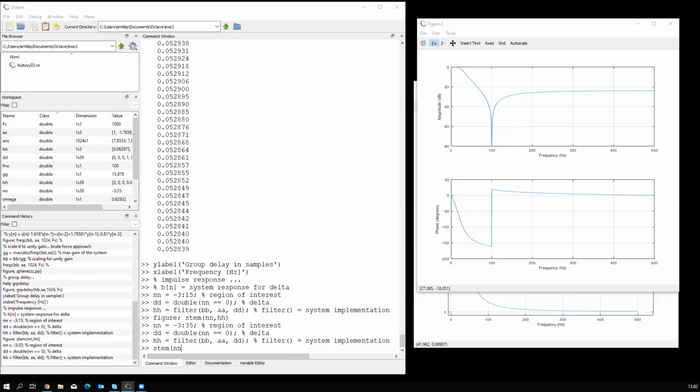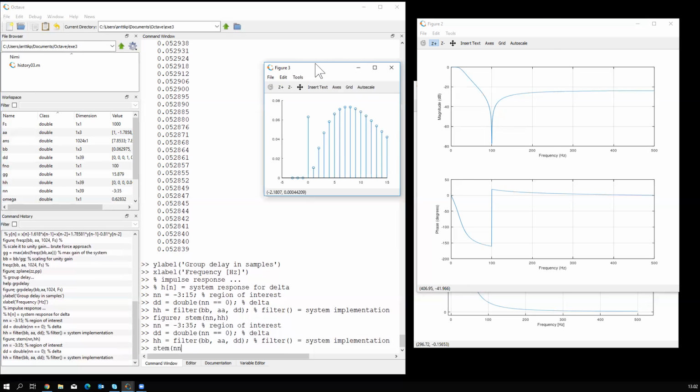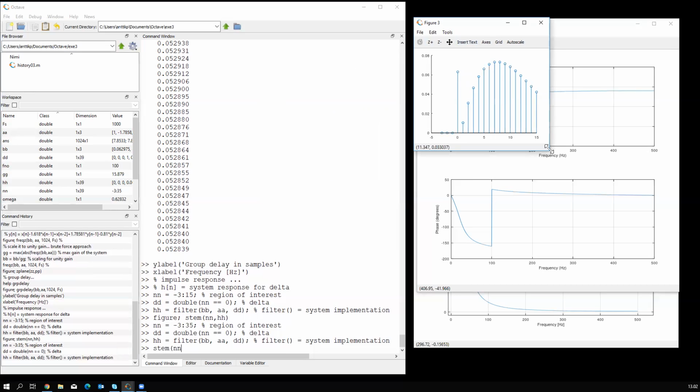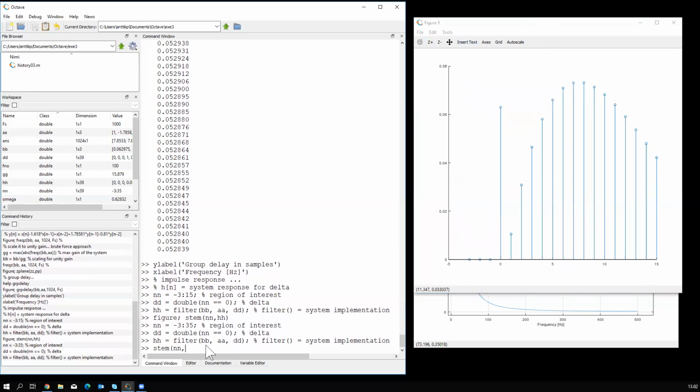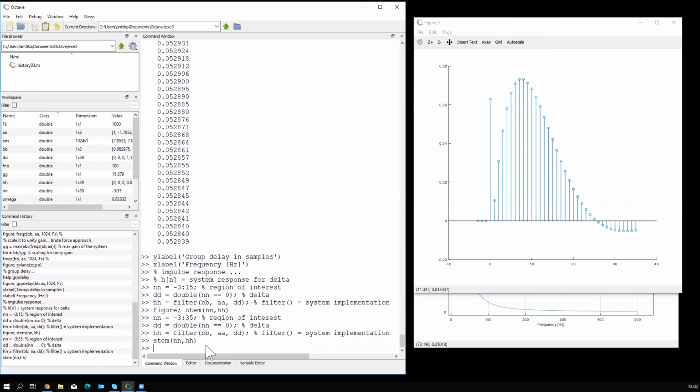And h to see how it actually decays. Wow, okay, that's interesting. So it goes like that and overshoots and then undershoots. FIR or IIR? Definitely IIR. First of all, the poles are not at 0 anymore. That also already tells me. But actual proof will be here.